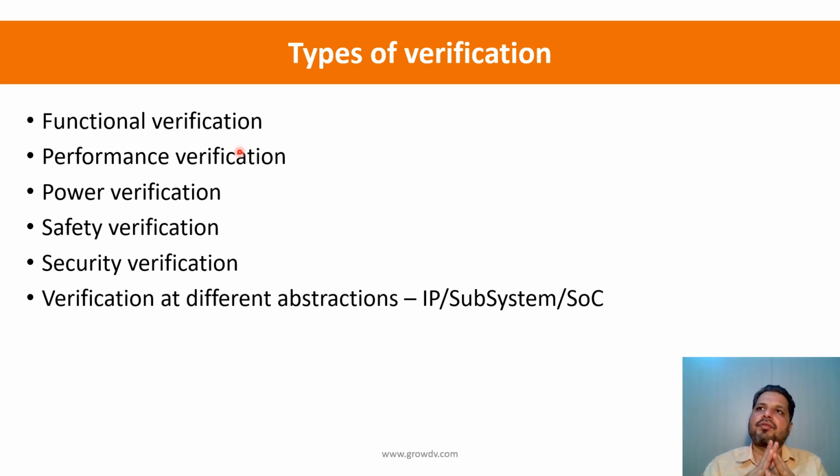So what performance verification typically does is create certain specialized test cases, and they also provide additional instrumentation within the functional test bench to extract the performance metrics, to check whether it has met the necessary requirements. So they run their own set of regressions to check whether the performance targets are met.